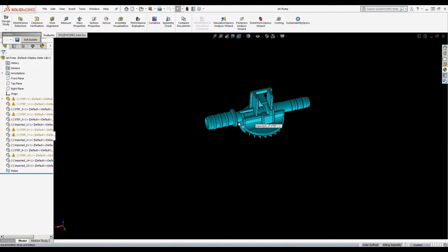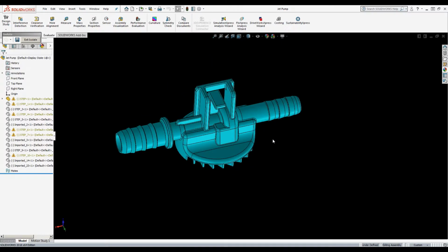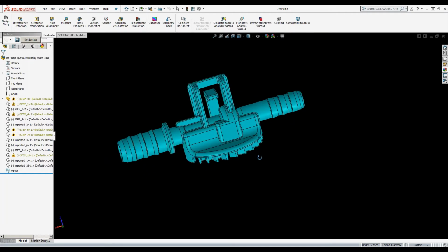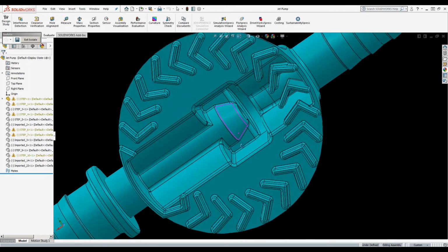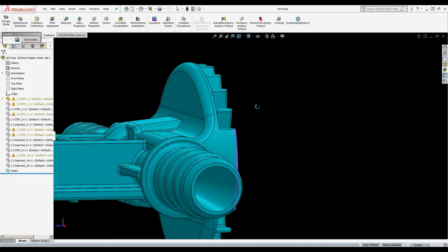All right, so barb features are pretty common among plastic parts. Typically, most customers at least cannot have a parting line anywhere on the first barb, just due to whatever they're putting over it, silicone tubing, any way to reduce the risk of cutting open any tubing that's attached to it. This part also has a couple undercuts, but this part is more focusing on the barbs. There is some intricate shutoff here, coming from this side to this side, tapered wall.